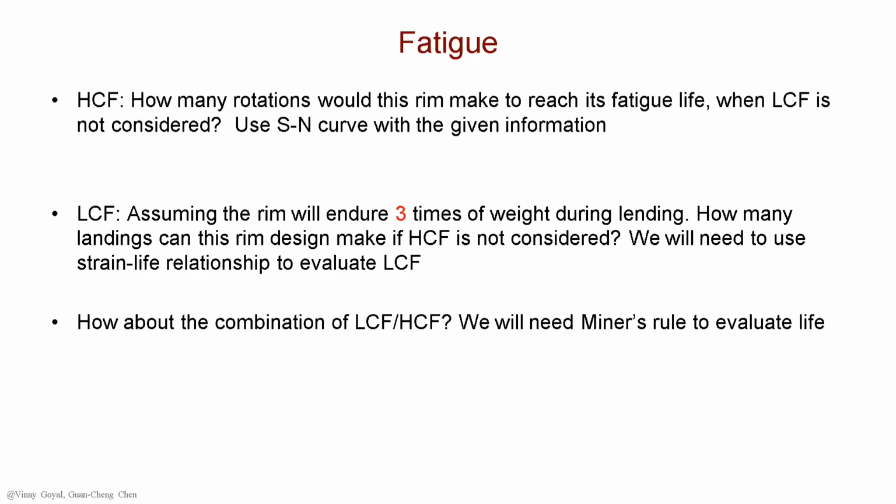We'll then have to use the strain life relationship for this analysis. And how about the combination of low cycle fatigue and high cycle fatigue analysis? You'll have to use Miner's rule to evaluate life. That's the hint I'll give you, and I'll let you think about it.